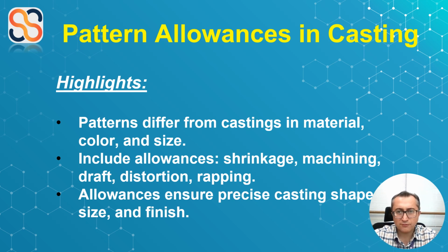Another important feature is the draft allowance. Patterns have slightly tapered sides, so when we pull the pattern out of the sand, it doesn't damage the mold walls. Without a draft, the mold might crack or the pattern could even get stuck.